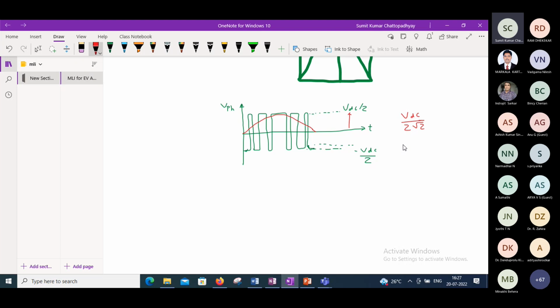So this is an indication. If this kind of PWM voltage appears across a magnetic component, finally, the loss components, if we analyze, there will be an effect on hysteresis loss and eddy current loss, and how it will be, we're trying to find it out.